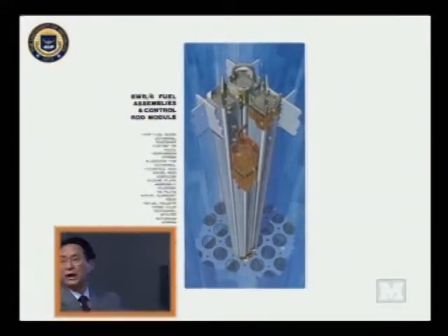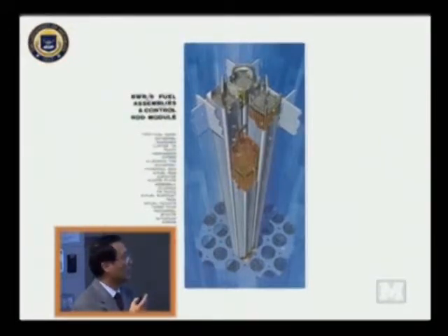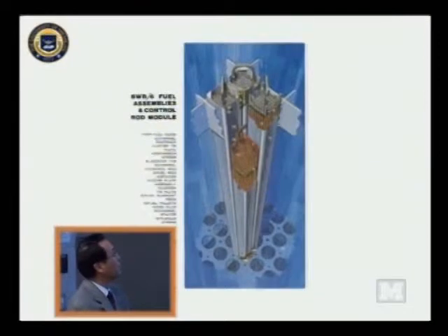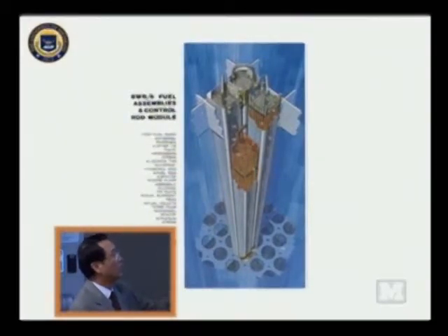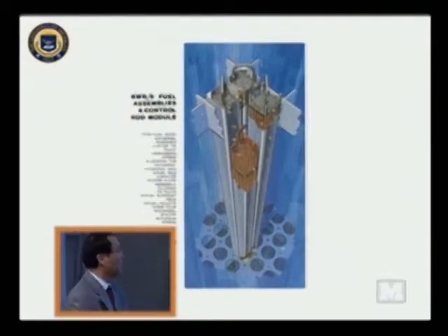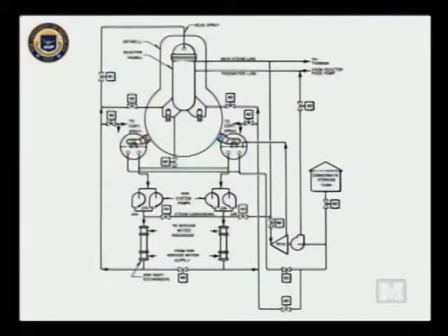And this zirconium cladding played an important role eventually in the evolution of the accident. I would say the event is a station blackout event for the reasons that I'll describe in a minute, rather than a pure, simple accident. And what we have also illustrated here are cruciform-shaped, cross-shaped control blades that are inserted from the bottom of the core into the lattice of the fuel assemblies we have. So now I have schematics of the safety systems that exist at Fukushima site.